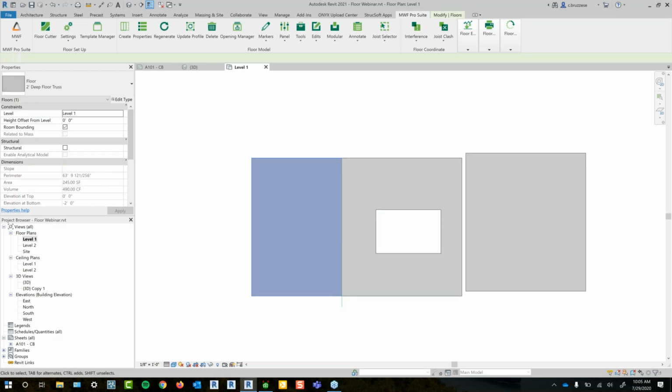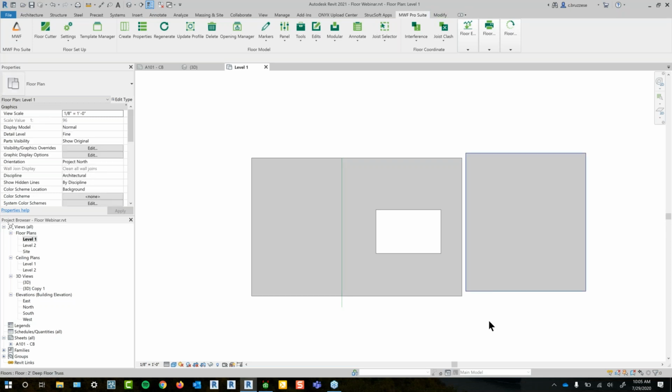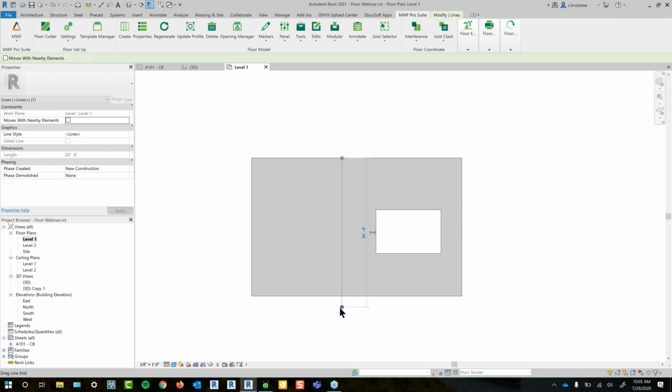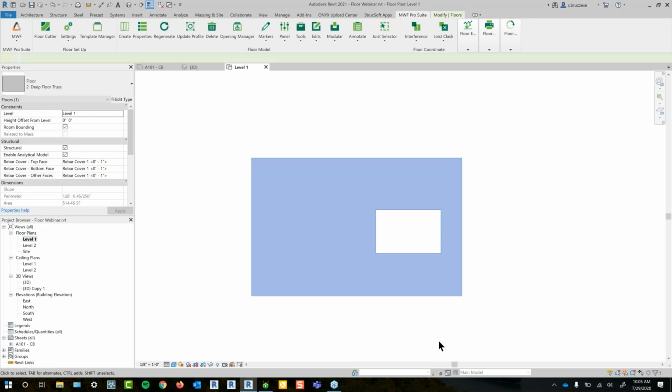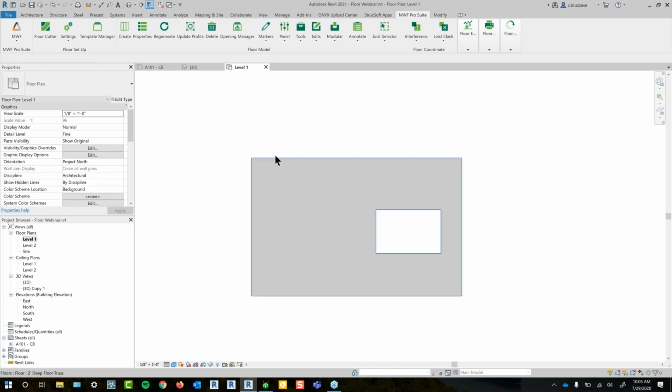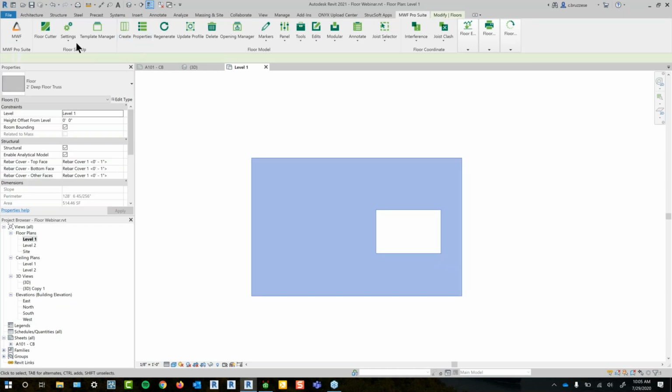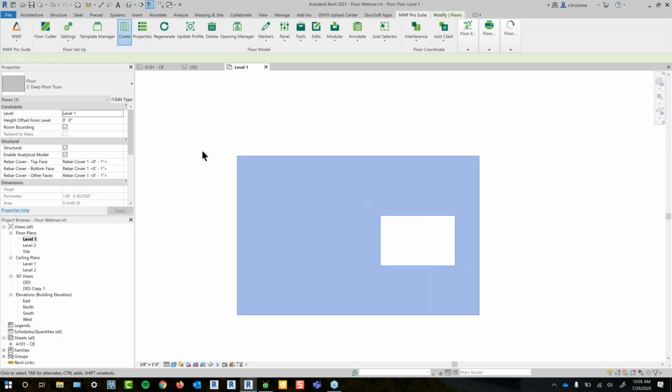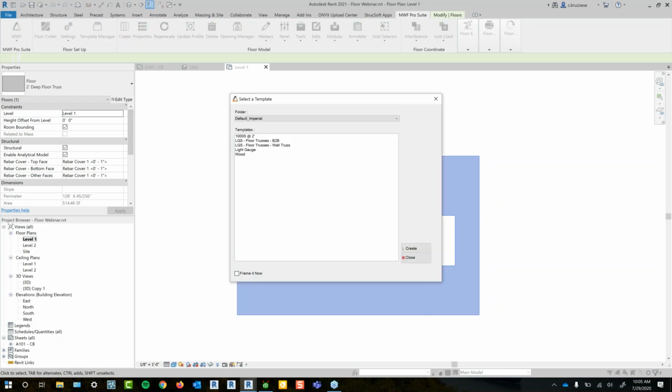So what you can do if you don't want to go about this method for splitting is that once the panel's created, we can go ahead and split it with the nodes. So just to reiterate, if you've just got whole floors, maybe without openings, I'd still probably go this route. But if you're restricted to keep the model as is, or if you've got a few openings done with the profiles, then I think the node method is probably the way to go.